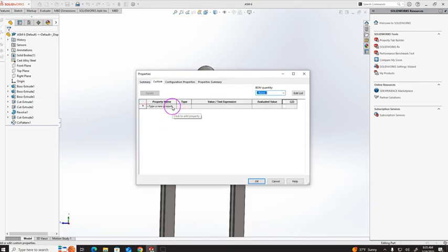And here you have to specify the property name. So if you click on this first row, you will see part number, then the revision, material, weight, finish, stock size. Okay, so all those attributes or the properties of the drawings are available, so you can link that. If you choose any property, that property will be there in the drawing.